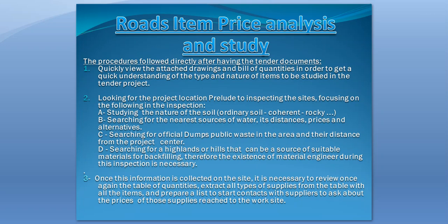And later on, he must look for very valuable information that will later help him to analyze and put the right price in the tender BOQ. First of all, after taking an idea about the items in the BOQ, he must inspect the site.